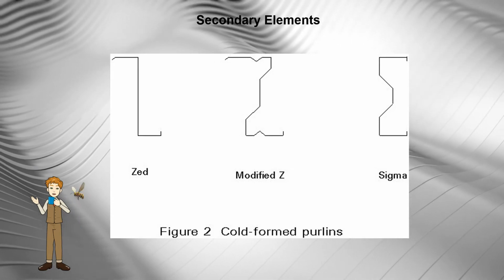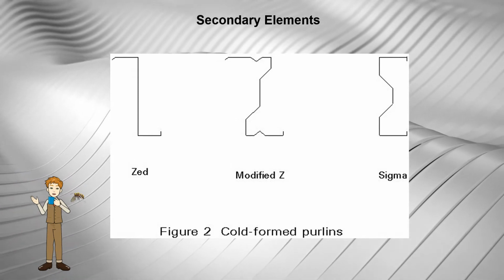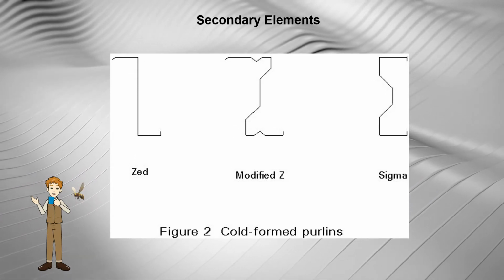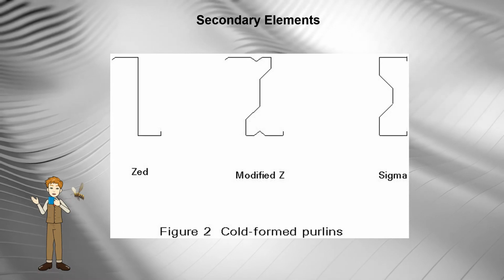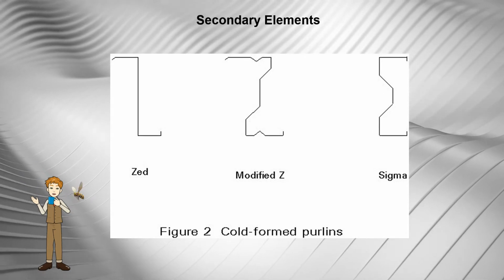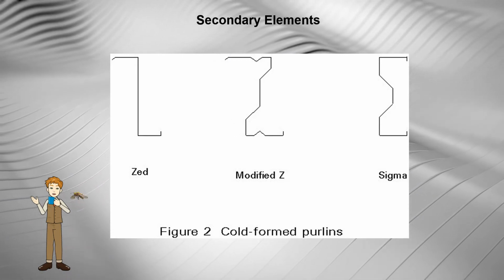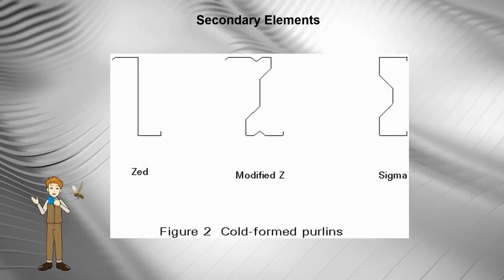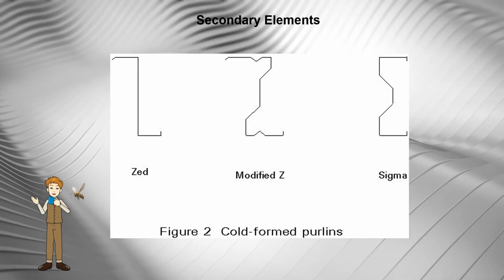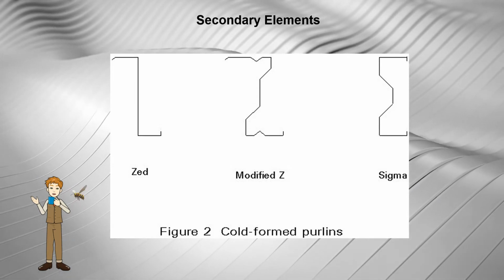Generally, the cost breakdown of various elements will be cladding at 50%, purlins and rails at 10%, the main frame at 30%, and the foundations at 10%. These figures are, however, indicative, as clearly there is considerable variation in specification and cost of the cladding, which is the largest single element.